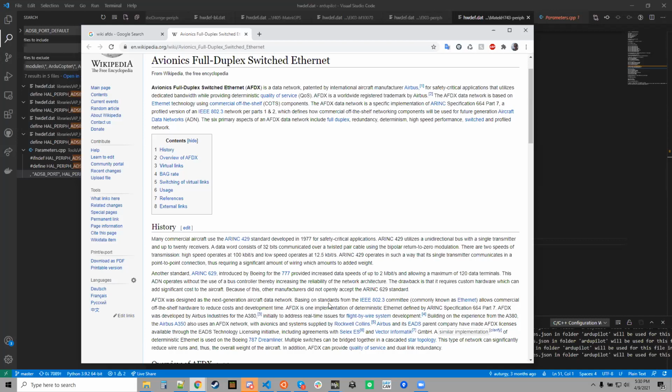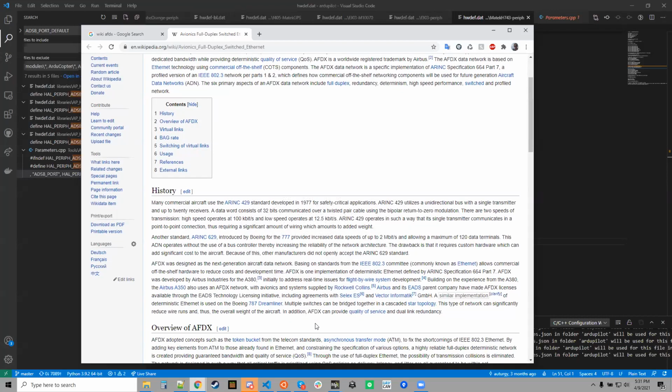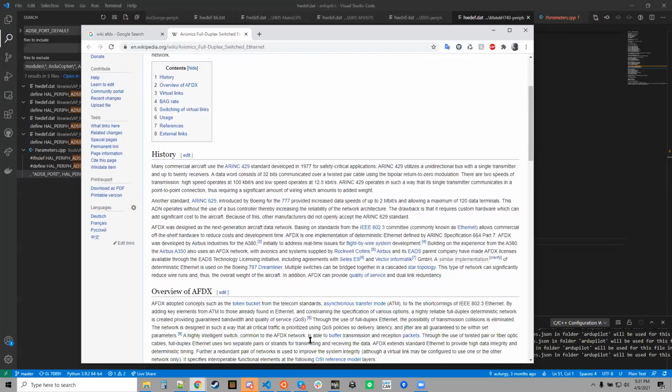Just when I see Tom wiring a whole aircraft up with CAN, it's not outrageous to imagine that somebody at some point would want to hook up an AFDX component, although they're hugely expensive. A really high-end drone might want to work with an ArduPilot flight controller or something like that. If it's 802.3, then that's super standard. It's just a matter of the data going over, I guess, and timing. But existing hardware seems to do it. It opens up a high band. You can get 100 megabits per second and low latency. It would be really great to have.